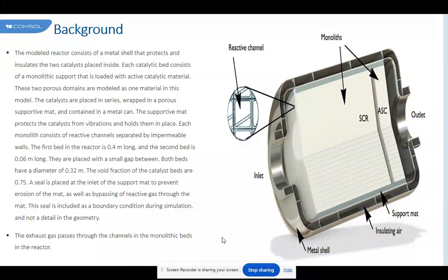NM requires further attention. According to the data in this simulation, the characteristic washout length in the 400 per 6.5 monolith is almost 49% longer than the one in the 900 per 2.5 configuration. However, according to the local values observed in the results, it didn't lead to significant differences in the effectiveness factor in this section.